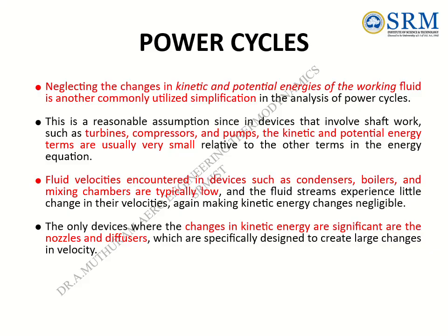Fluid velocities encountered in devices such as condensers, boilers, and mixing chambers are typically low, and the fluid streams experience little change in their velocities, again making kinetic energy changes negligible. The only devices where the changes in kinetic energy are significant are the nozzles and diffusers, which are specifically designed to create large changes in velocity.